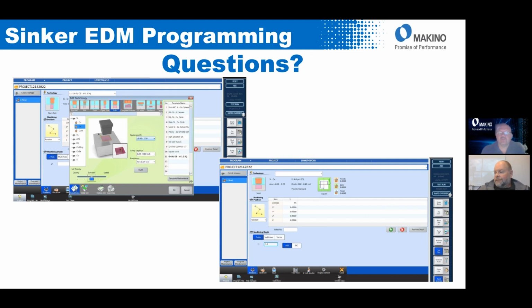All right. Very good. Skip has a question here. He said he saw a template folder, and can you use that to copy programs and adjust it per job? In part 2, we're really going to get into the template side a little bit more, but just a basic explanation: for the templates, we go through multiple pages to set up the technology, electrode material combination, spark area, the reduction, orbit pattern, those types of things.